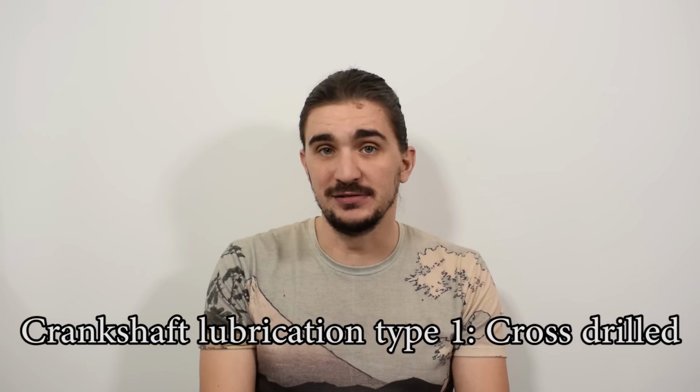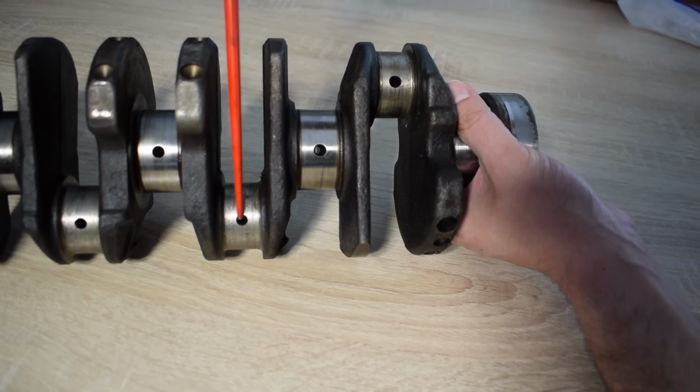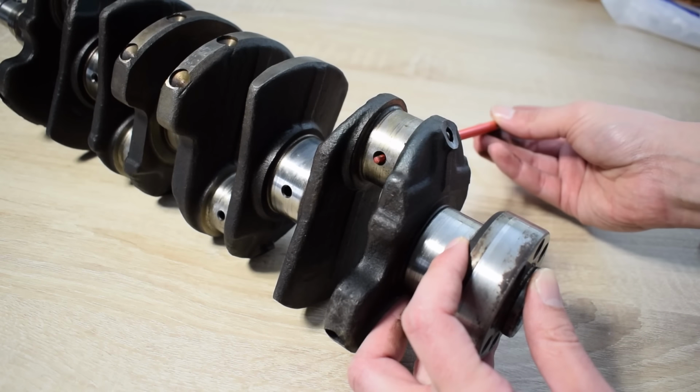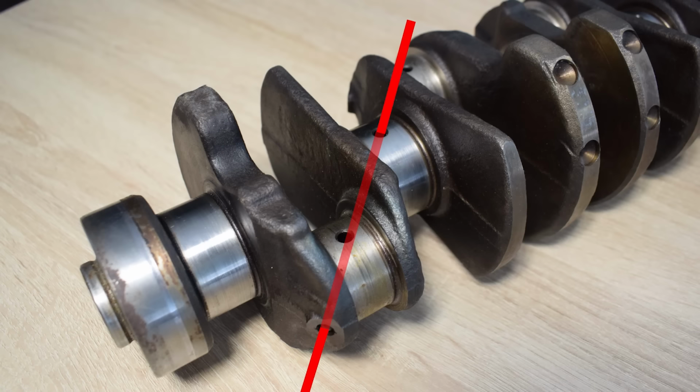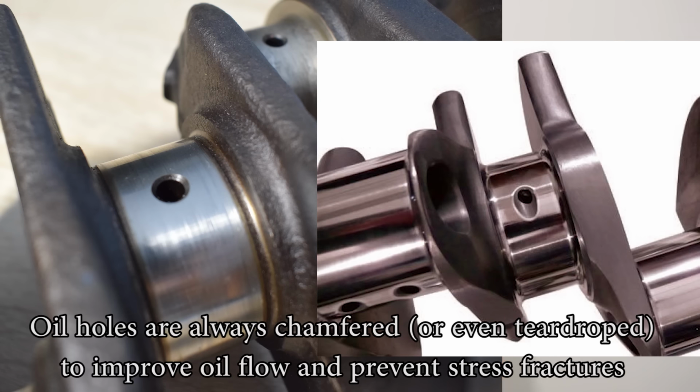A typical OEM crankshaft is going to be cross-drilled. And this means that the main journals and often the rod journals will have two oil delivery holes in them. The journals are in effect cross-drilled. And this is followed up by a drilling at an angle from the rod journal to the main journal to create a path for the oil between these two journals. The drilling is then capped off like this. Oil holes on both the main journals and the rod journals are pretty much always chamfered. If you ever see a non-chamfered oil hole on a crankshaft, which is very rare even in cheap reproductions, walk away.